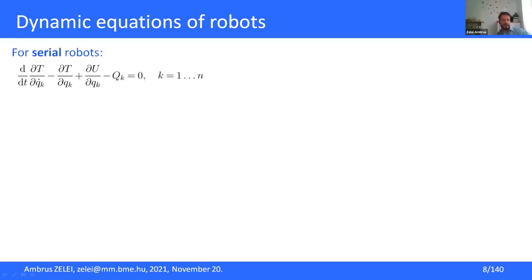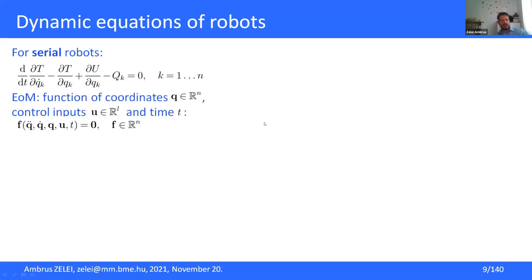So if we have a model, then we can predict the motion if we know the activated motors and actuators. And I hope everybody knows here the Lagrange equation of the second kind. There is the kinetic energy and potential function. So it's usually taught in vibrations course. And what you obtain by using these equations is a function of the coordinates, the generalized velocities and generalized accelerations,